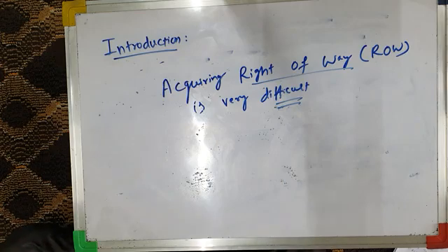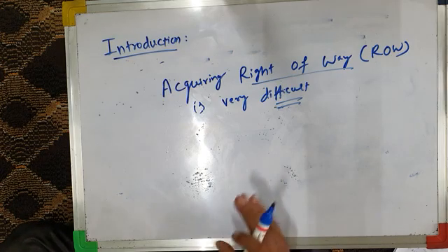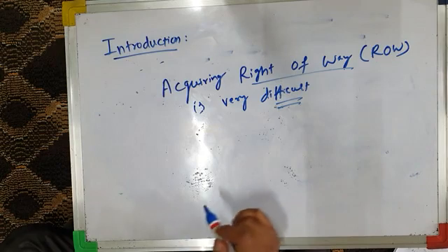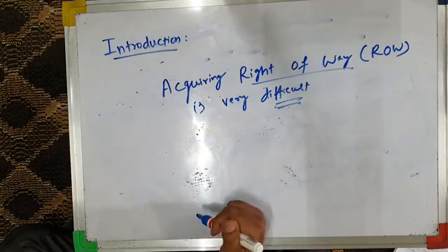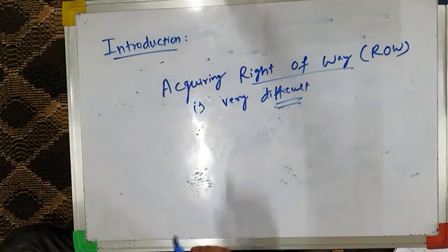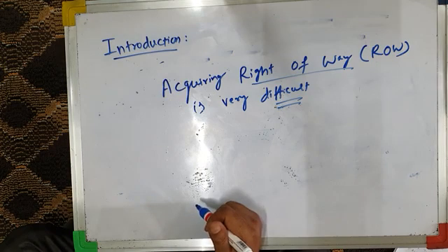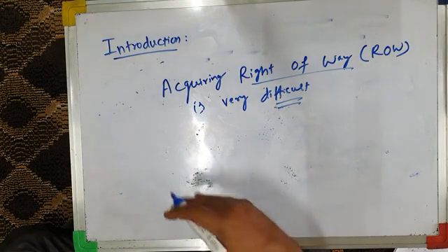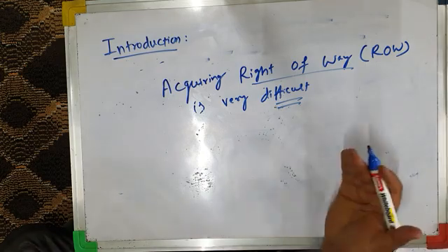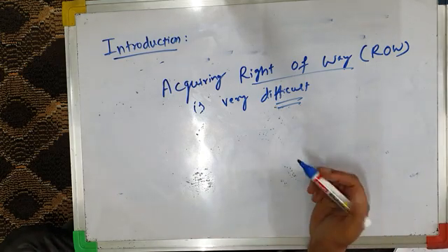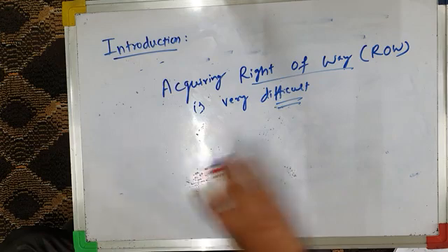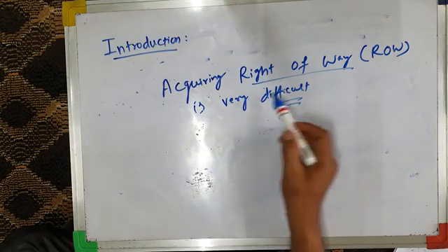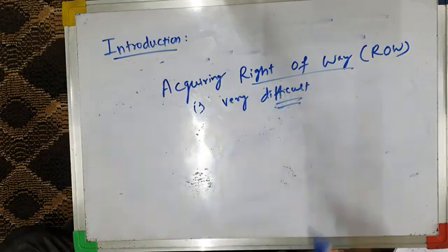And then, since our transmission systems are mechanically controlled, the response is slow, and hence that will also render it unstable. And finally, for meeting the increased power or load demands, you have to lay new transmission networks, for which you have to acquire the right of way, which is difficult nowadays.